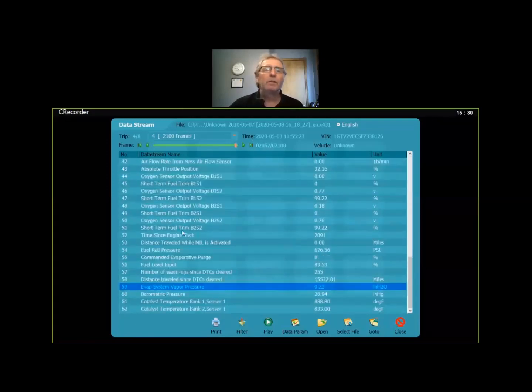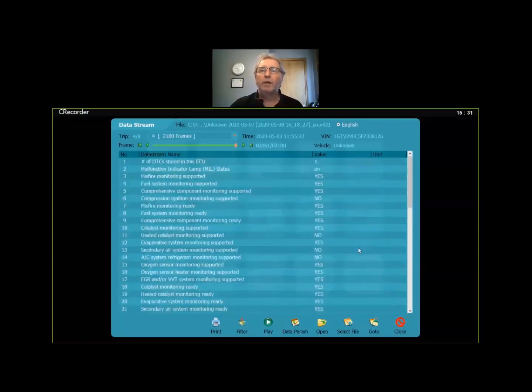And if we look at, let's look at purge, commanded evaporative purge, that's on 0. Let me back it up a little bit. All right, it had been purging. So I'm going to say that this is the time right here when the purge shuts off, and right away then our pressure goes from negative to a positive. That's when this monitor gave up and failed, right at frame 2060 right there.